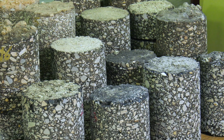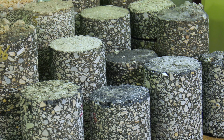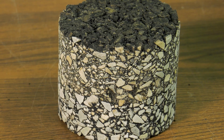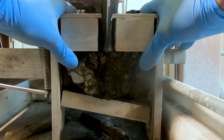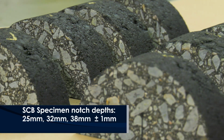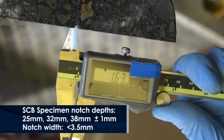For the field cores, the dimensions of the cores should be 150 mm in diameter and between 38 and 60 mm in thickness. If the thickness of the core is greater than 60 mm, it should be trimmed to 57 mm and cut similar to the laboratory prepared test specimen. Next, cut a straight vertical notch along the axis of symmetry of each semicircular specimen. A minimum of 4 semicircular specimens should be tested at each notch depth of 25, 32, and 38 mm. The notch width should be less than 3.5 mm.